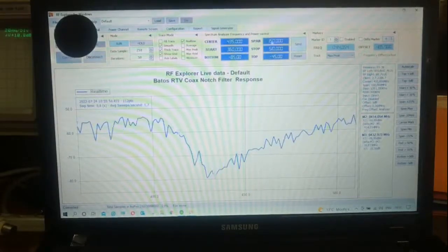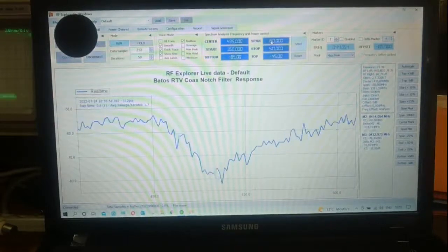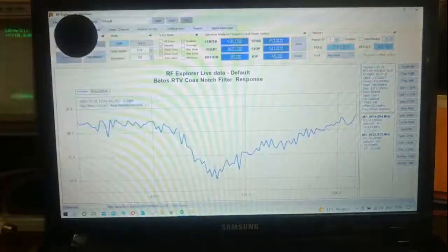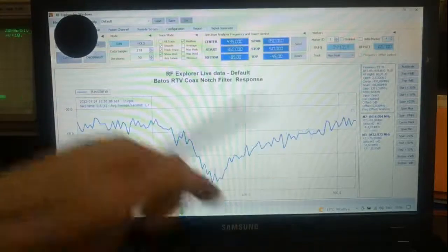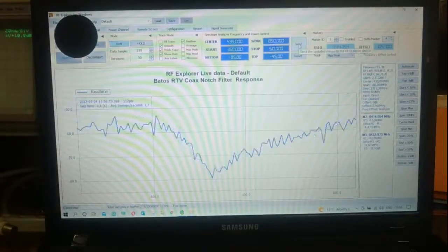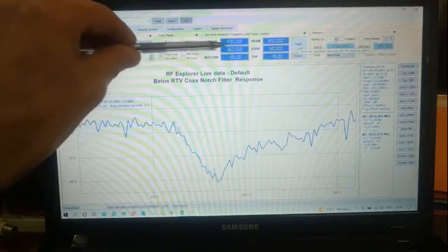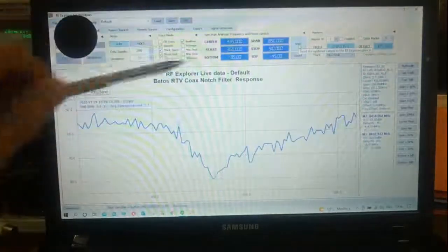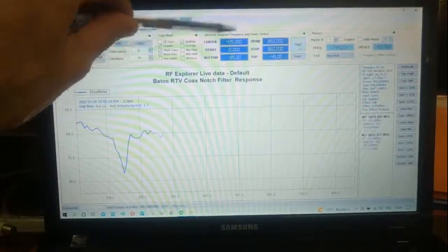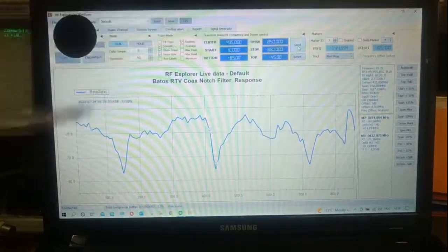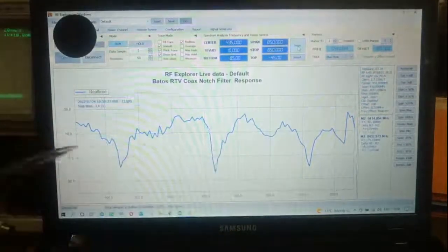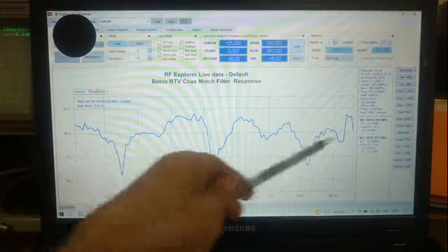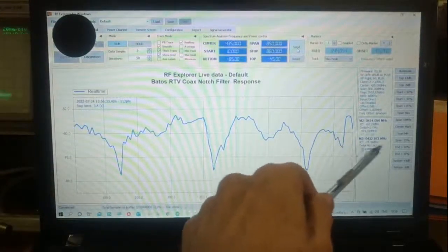And the easiest to demo is, I'm just going to increase the frequency span from 150 megahertz. If you look at it over here, I'll increase it, say, to 850, and you can see how many peaks in that particular bandwidth, which is from starting 360 to 850. So it's going to be from 10 megahertz to 860 megahertz. And as you can see, this is the actual notch filter, okay? Point number 3, which is 432 whatever megahertz.